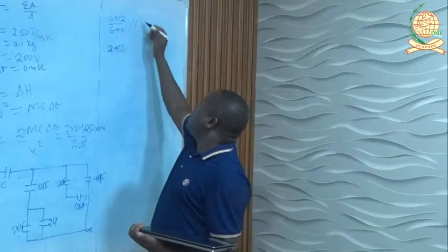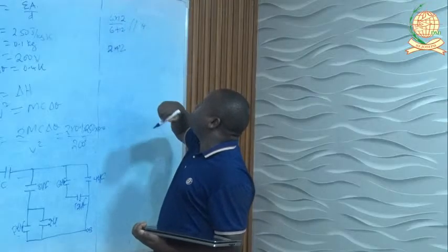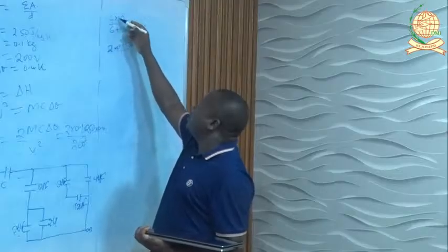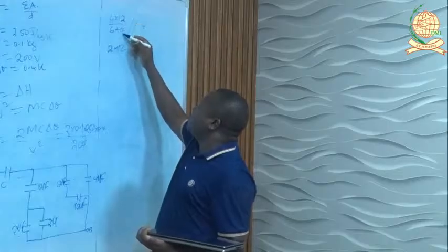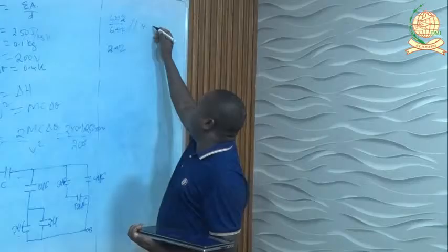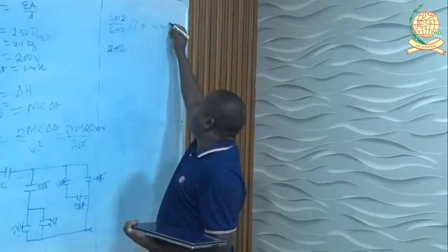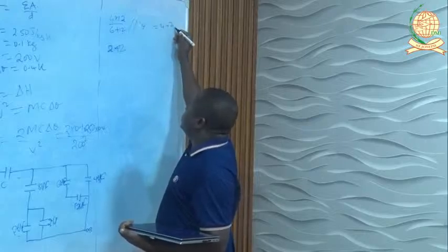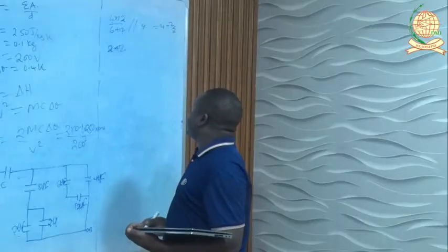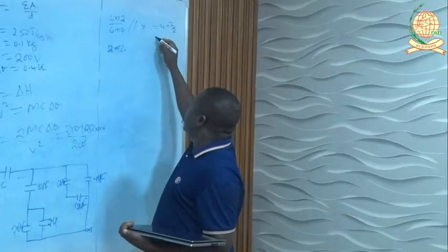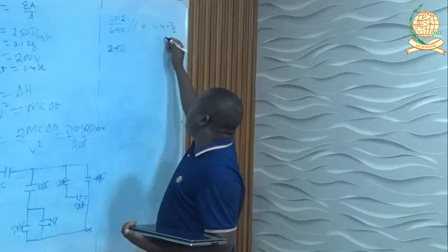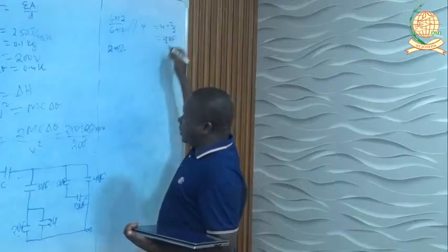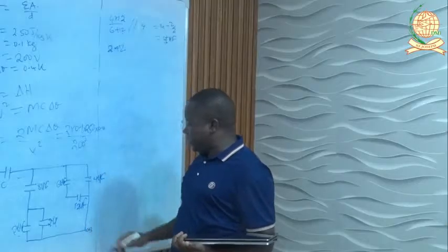So here, what is the total? This is equal to 12 by 6, 1, 2. This is 2. 3. So 3 plus, I'm getting 4 plus 2 over 3, which actually is equal to 12 plus that one, 14 over 3 microfarad. The total from there to this point.